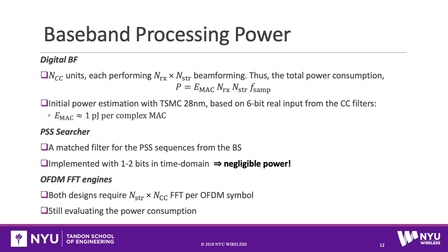Similarly to other works, we found that the PSS search can be implemented using very few bits. At this resolution, the PSS can be implemented in the time domain, and initial calculations show that the power is negligible. At this point, we are still evaluating the power required for the FFT engines for the OFDM processing. However, it will be the same for both of the designs.